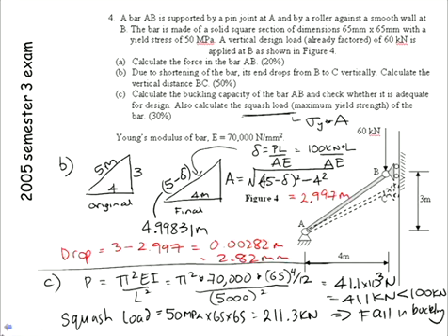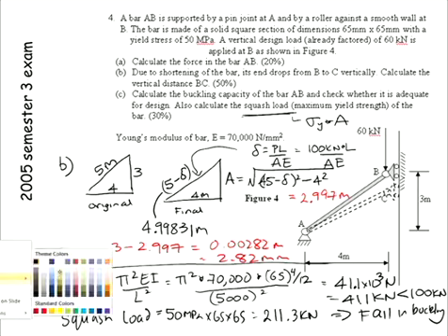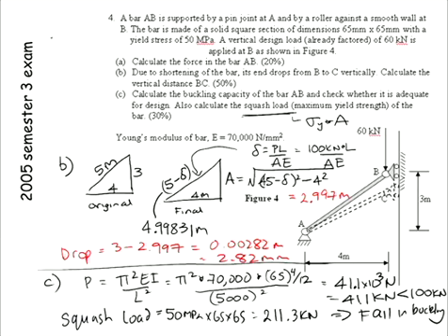So if we actually look at our P on L curve, we know it looks like so. We're saying this upper limit here is our 211 kilonewtons, and we're currently at 5 metres long, sitting on that point in there on our graph.